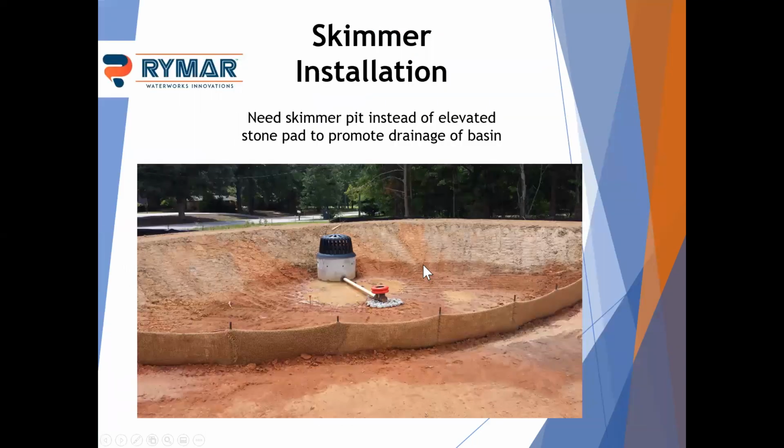Okay. You've probably seen some skimmers installed, but in case you haven't, I've got a couple of pictures here, things just to be aware of. So this is a basin, essentially one of our older model skimmers, but anyway, it was obviously newly constructed, just put in, had first rain after installation. It looks okay. The baffles are in, slopes are tracked. Obviously haven't seeded and strawed it yet and gotten any vegetation.